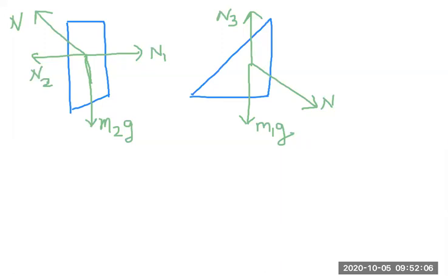If you cannot work out the direction of acceleration by visual inspection, then you have to write the acceleration of the object as ax along the x-axis, ay along the y-axis, and this x and y-axis you can choose any which way you want, but the best way would be horizontal and vertical, right?